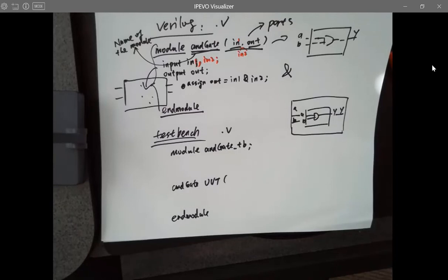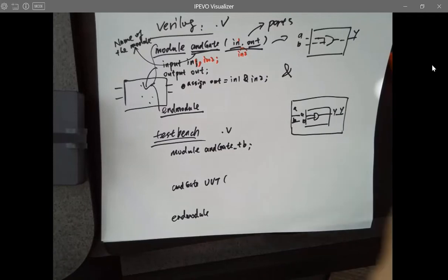The LEDs are inputs or outputs? Outputs, because they cannot send a signal. They receive a signal and indicate if it's a 1 or 0. So the LEDs on the board can be used as outputs, and the switches on the FPGA board can be used as inputs.